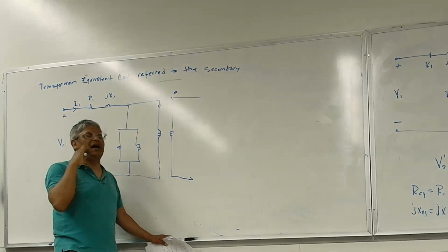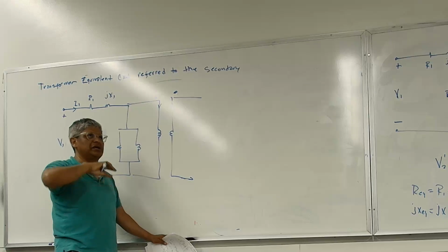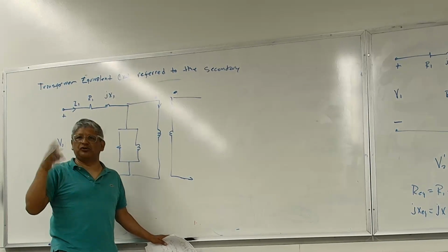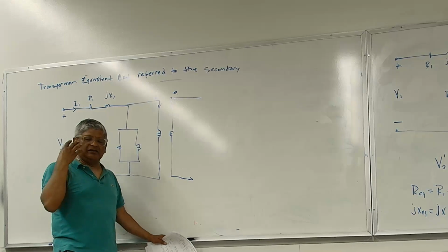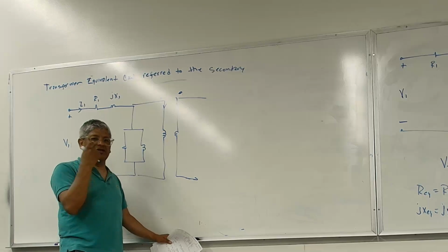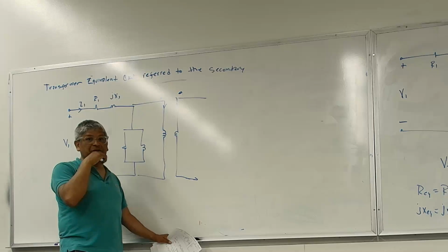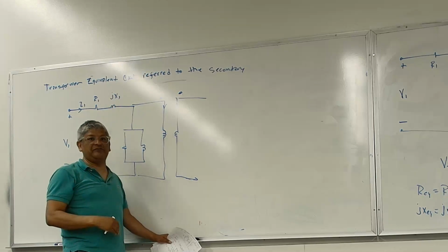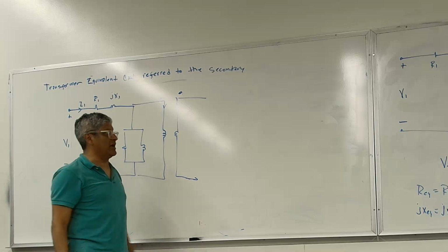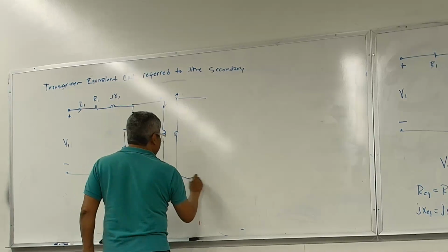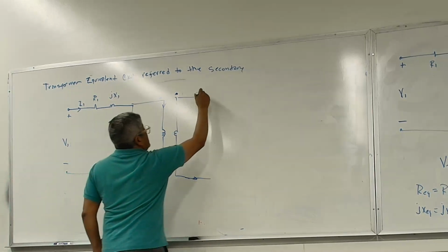Especially in three-winding transformers, if you don't pay attention to that, and somebody tells you, hey, I want you to wire 3 single-phase transformers and make me a 3-phase transformer, and you're not careful with those polarities, you can actually blow out the transformer. Because when the transformer is supposed to be on the peak, it's on the other side, so you can have this potential difference between, and hence you can have a short circuit. But these dots right here are not just there because